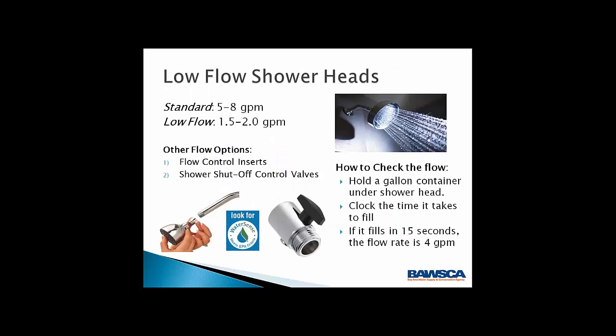So given that showers are the single biggest water user within the home, a very easy step that you can take to reduce your water use is to make sure that you have a low-flow shower head installed. Standard shower heads use between 5 and 8 gallons per minute. Low-flow options use 1.5 to 2 gallons per minute. There are quite a few really nice WaterSense certified shower heads available on the market right now. And depending on which community you're in, your water agency may be able to provide you with one.